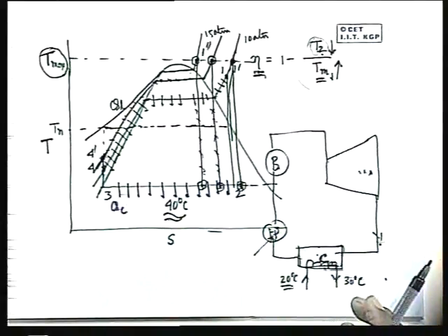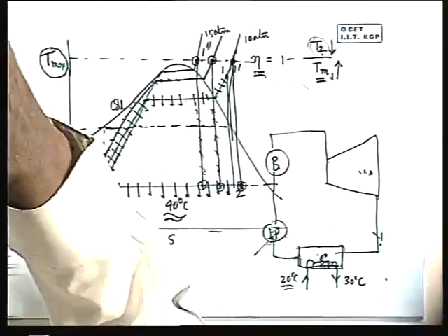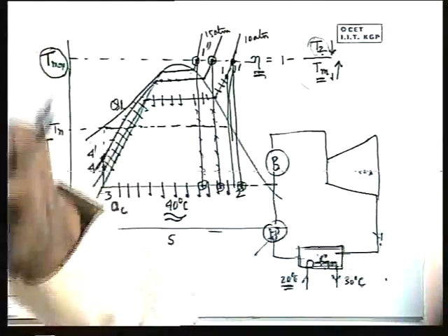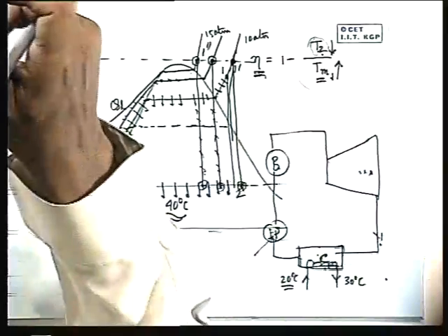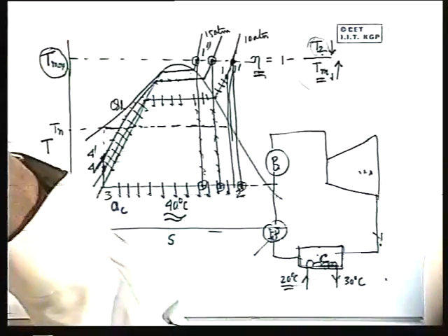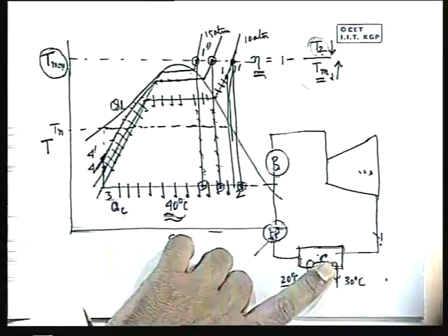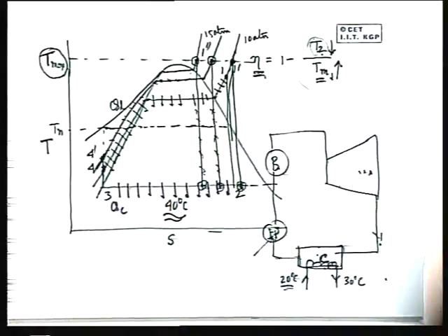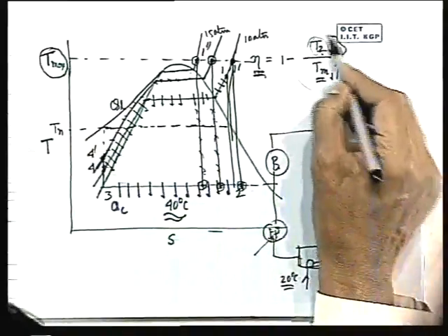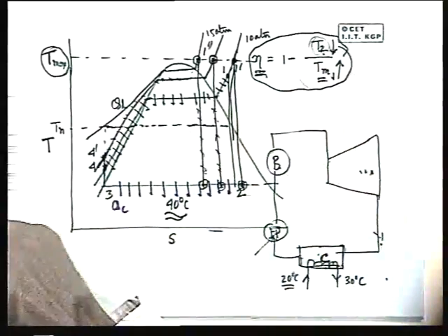You want to condense a certain amount of steam. So coolant temperature has to be low, because heat transfer is possible only if there is a negative temperature gradient. Heat flows from a high temperature to a low temperature. That means by chance you create a vacuum whose value is, for example, 0.05 atmospheric pressure. You are very thrilled, and you see that the saturation temperature is 20 degrees Celsius. So you are very thrilled by seeing this equation, efficiency is enhanced by a great amount.